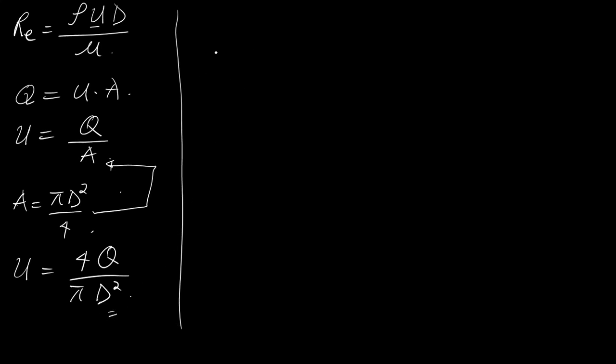Having gotten this, we also know that in the field, flow rate is always being recorded, being measured in standard meter cube per day. So this expression, the Q, is the flow rate at the condition of the gas. Now for the standard condition, for us to relate the flow rate at standard condition with the flow rate of the gas at any condition, we have to apply the law of conservation